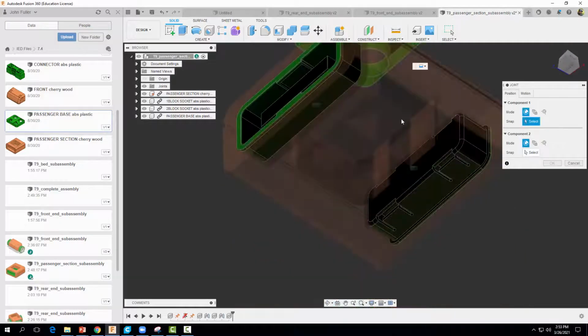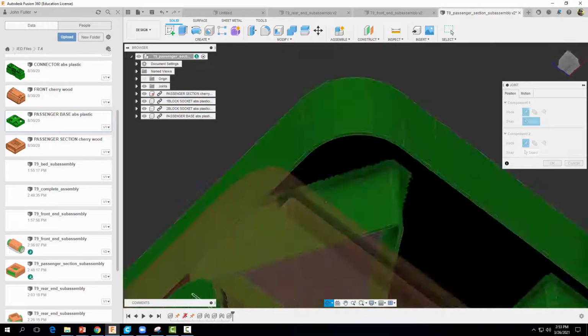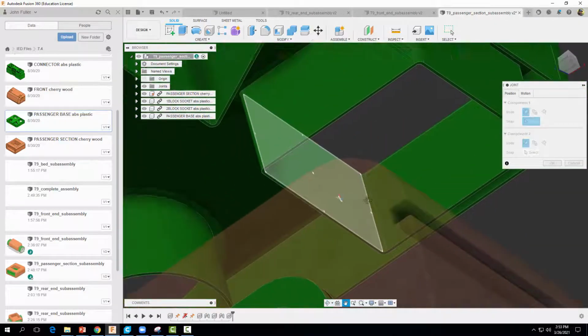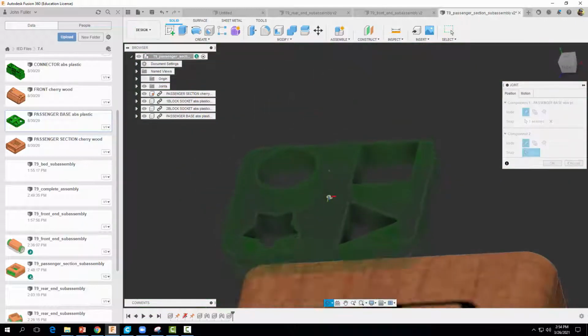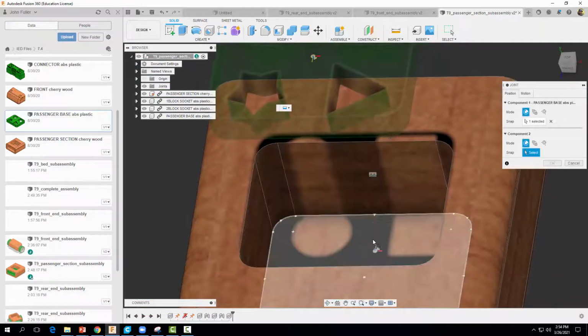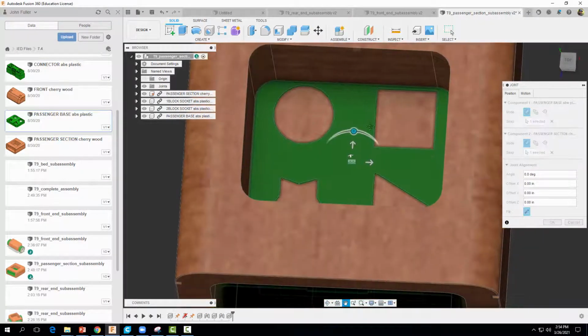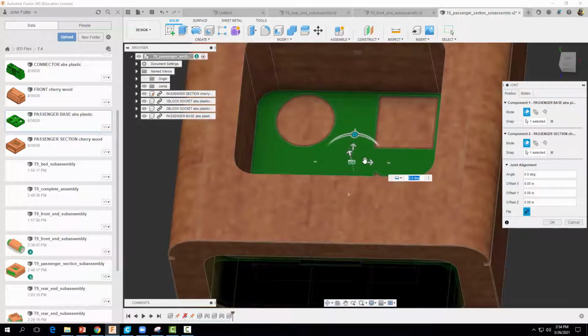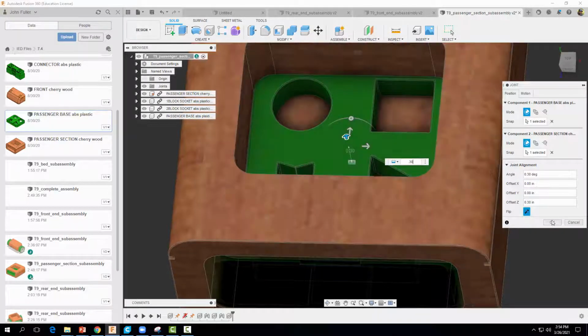Okay, I'm going to rotate my part around. I'm going to zoom in here. I'm going to find that center point of this, which is kind of hard to find, but it's right there. Okay, and now I'm going to find the center point on the bottom now. Right there. Okay, now it's too far down, and remember that distance, so we're going to move it up 0.30 or 0.29 works too. Okay, offset it 0.30, select OK.